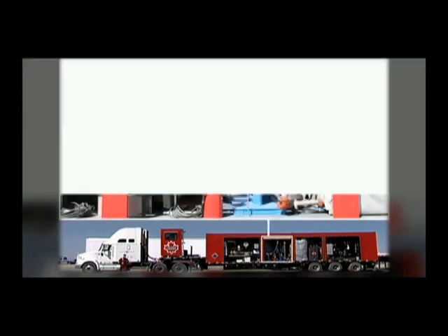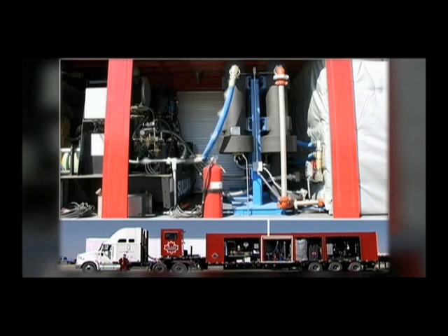In the pretreatment system, the air passes through an oil separator that removes oil and/or coolant from the air to levels of 3 to 7 parts per million. The oil-free air then enters the air aftercooler, which causes water and oil vapors to condense. Separators and filters remove condensate and larger particulates as the air moves on to a coalescing filter that removes fine aerosols and finer particles. The air is then reheated before entering the carbon tower, which keeps the air temperature substantially above the dew point temperature of air. When the reheated air enters the carbon tower, vapors are removed.